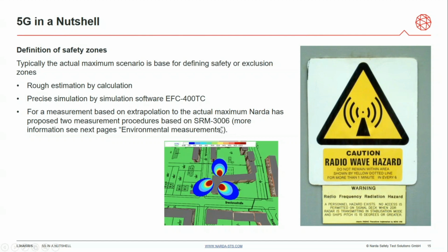For that, it's necessary to have the scope mode, that is an oscilloscopic mode. Technically, it's IQ streaming in real time. It's a level meter in time domain, so a demodulation of the baseband. You see the whole baseband like on an oscilloscope, demodulated on a spectrum analyzer, to check the uplink and downlink, to see if there are any effects of mobile phones in the uplink, which would corrupt the test result in the downlink. And the second method is a code selective method, which we are proposing.